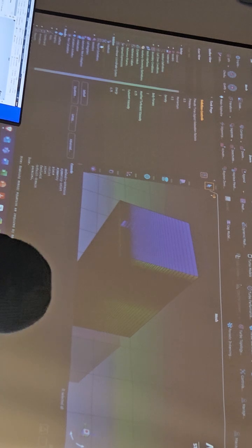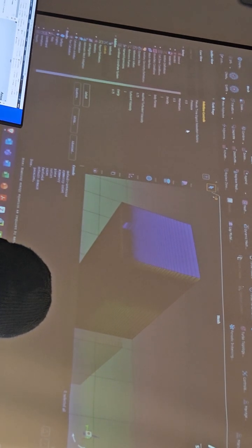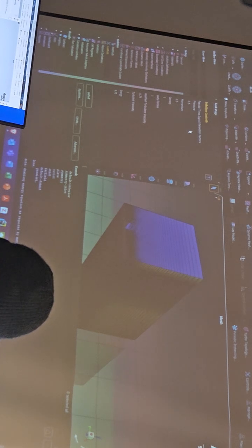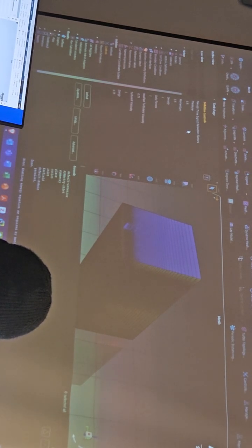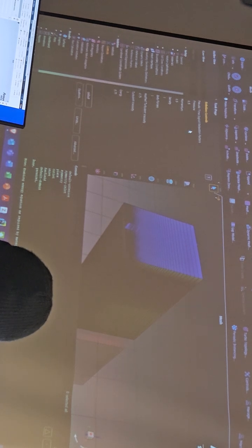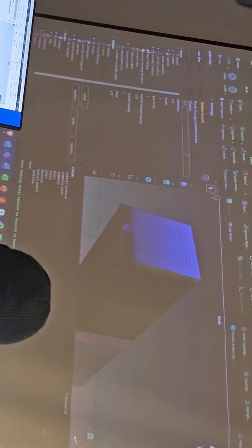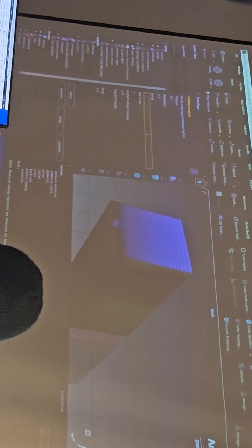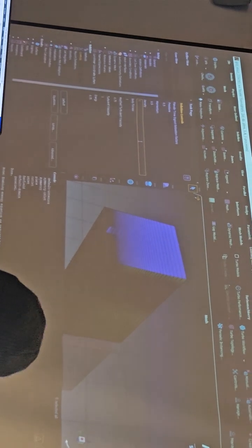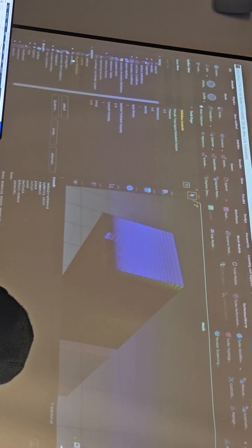Then in controls, we can leave it by default. These are also parameters that if you encounter some numerical instabilities, these relaxation factors can help to get convergent results if the problem is, let's say, numerically difficult to converge. But this is not the case, so we leave them like they are.